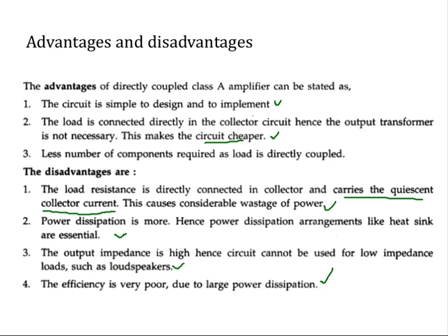So what is the difference between a voltage amplifier and this amplifier? The only difference is that since it is a power amplifier, it has to handle large voltage and current, and a power transistor has to be used. But because of RL, there will be huge losses occurring here, and efficiency is maximum 25% only.